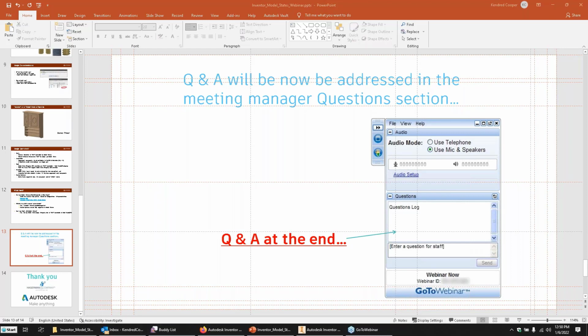As far as multi-body solids, it supports those. If you try to do a simplify, for example, you have the option to have an assembly simplified down to one part that has no faces or no edges between the components, so all the planar edges are merged. You have the option of keeping the planar edges. You have the option of breaking down each individual piece part into a separate solid. So it is fully supported by multi-body solids.